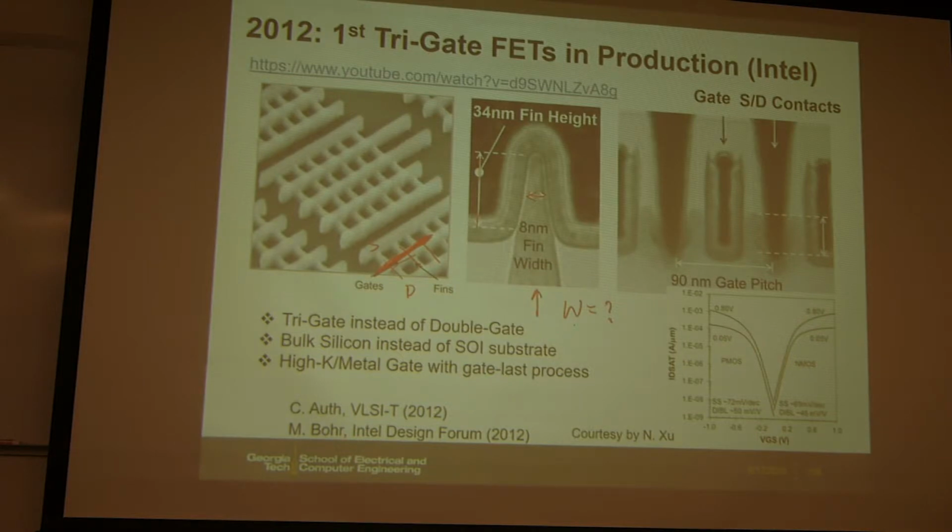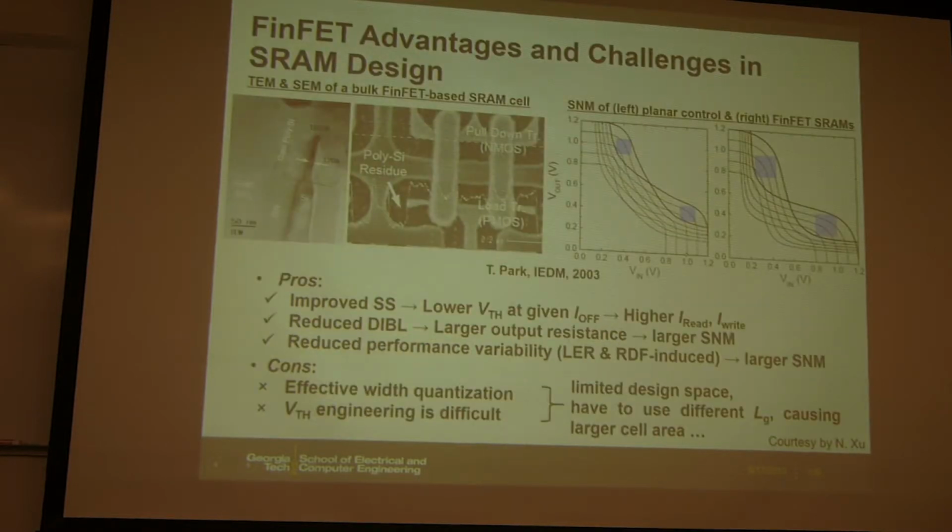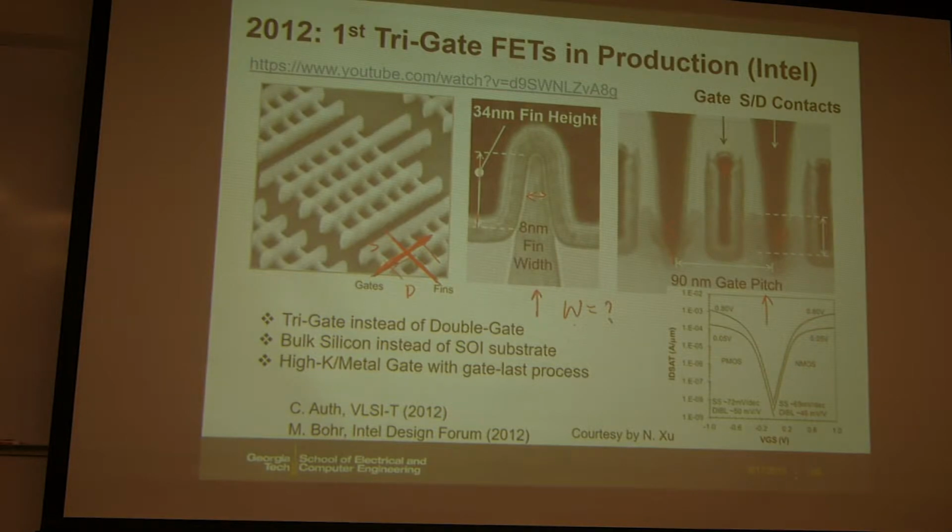And then if you cut this along the other direction here, then you get this figure. So this is from source to drain, and this is a gate, and this is the contact gate pitch as we discussed from source to drain here, and this is 19 nanometer CGP. And this is another view, which is you are looking at exactly this surface, and you have gate surrounding like this.